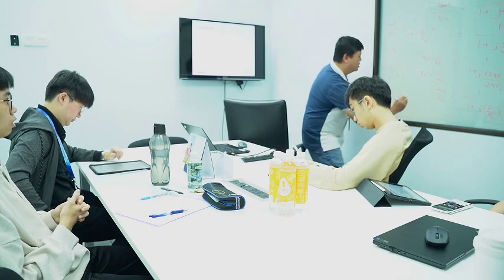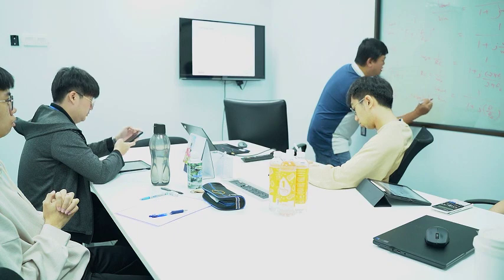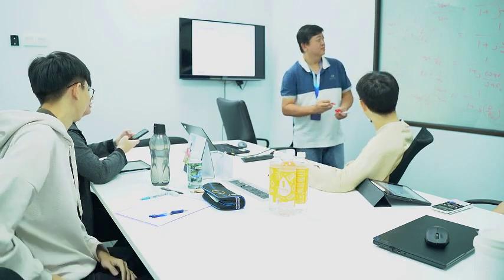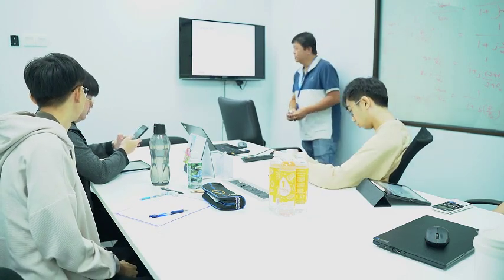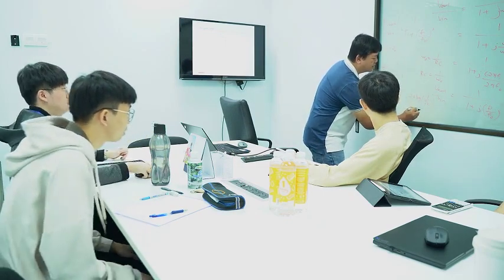You try to see, 20 log of 1 over square root 2 is how much? You try to calculate and see. Actually, 1 over square root 2 is 0.707, which is minus 3.01, almost minus 3 dB. This is how the minus 3 dB comes from.